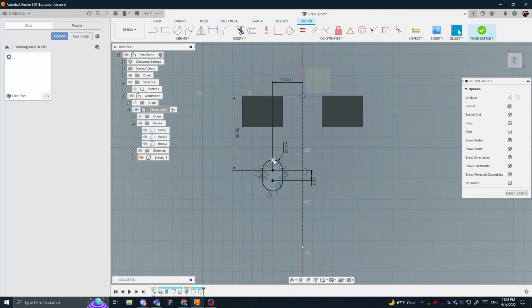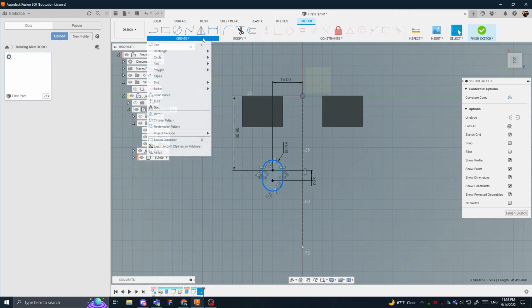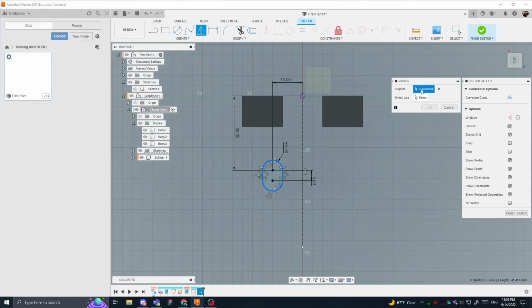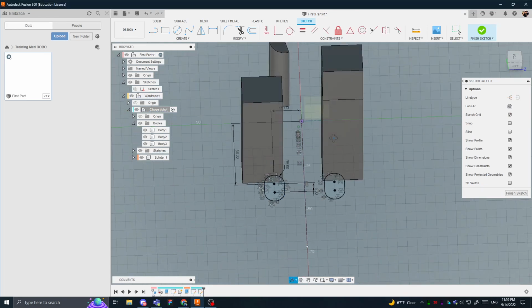This is what you want in parametric modeling, completely constrained objects. So that way everything can update as you go. So if I come in here later to 10, everything should be fine down the line with whatever you do. Now let me double click this to select the entire length, whatever's touching adjacently, so it can just complete the loop. I'll go to the mirror tool. I have my objects. I can also click on the dots here if I want to be fancy, and click on this line. Now I have my 2 sets of chopsticks.